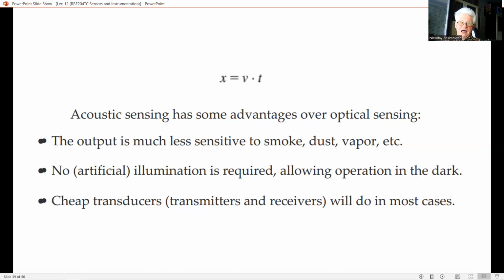In mechatronics, they mainly fulfill the task of non-contact measurement of distances and derived quantities. Similar to optical sensing systems, such acoustic sensing systems also comprise basically three parts: a source, a receiver, and a modulating medium. In mechatronics, the medium is mostly air.